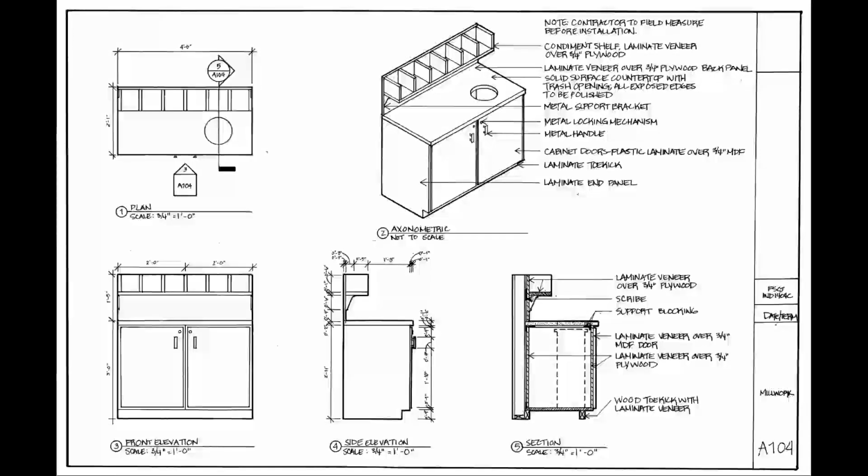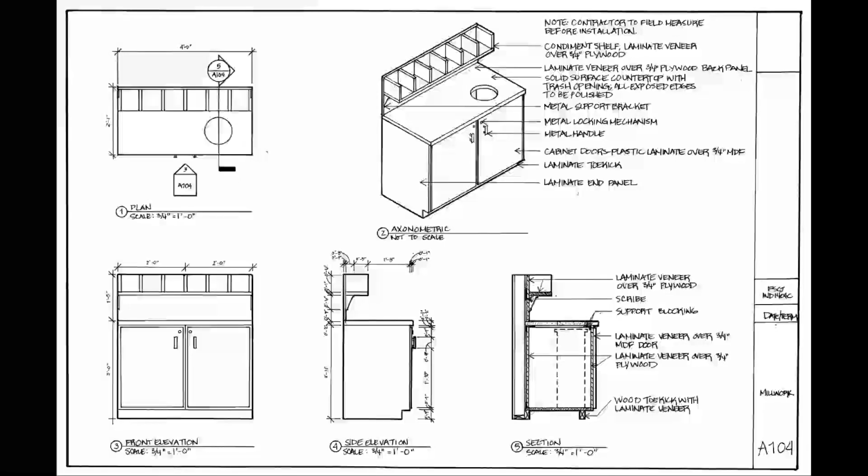And then you should be able to create a sheet that's got a really nice layout, that's clear with information, that has annotations properly placed without any duplication of information or crisscrossing of lines. And you should be able to now create your own set of drawings that shows line weight variation and hierarchy and just the right amount of information and detail.